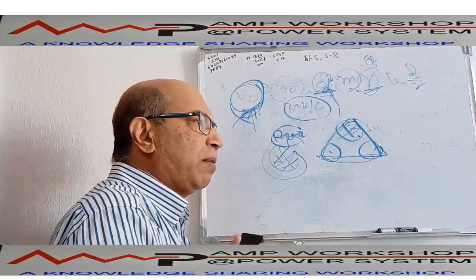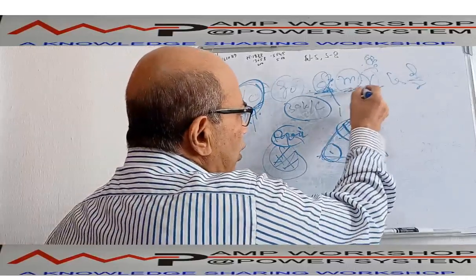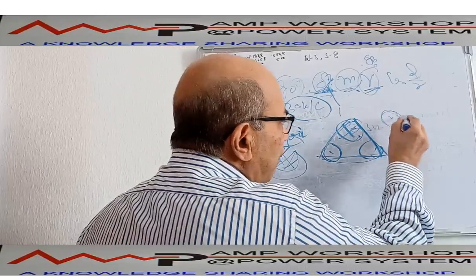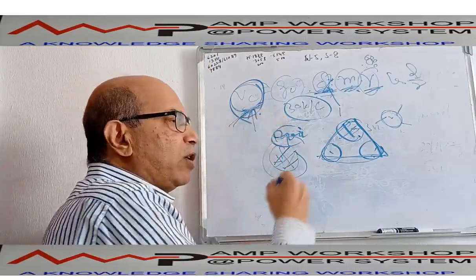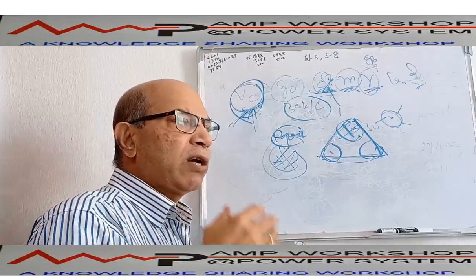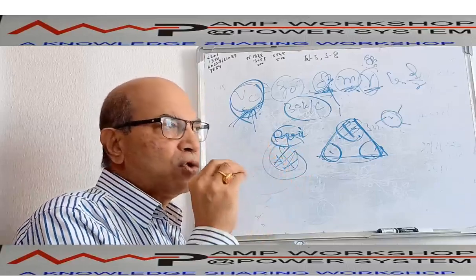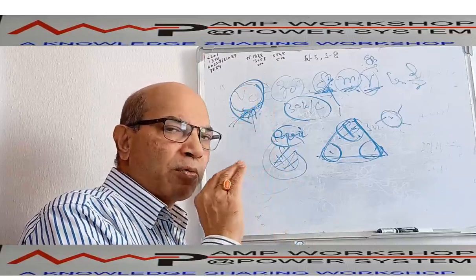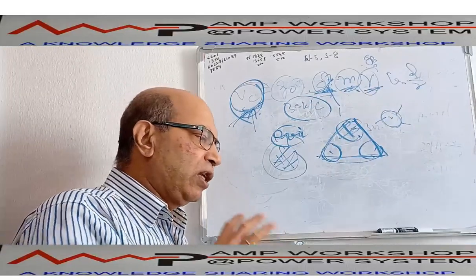And another point we have to keep in mind: corona discharge also depends on sharpness. You will see here, this M factor for a polished conductor is 1, but if the conductor surface is not polished or there is a sharp edge on the conductor, the M value will be higher and higher. That means the disruptive voltage will go down and corona discharge will take place immediately. That's why on any high voltage transmission line, any fine sharp edge will be minimized. No wire will be left out, no sharp edge will be there, all sharp edges should be properly polished. That is another requirement to avoid corona discharge. So these are the various